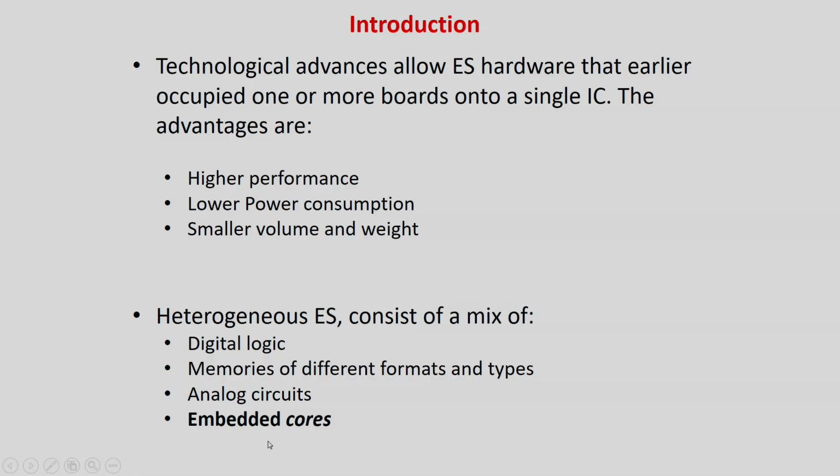Now if you have such a system, for some of the cores which I have designed, I have entire knowledge, I can put my DFT requirements, where to put scans etc., and I can make my life easy for testing. But think of the other cores which are purchased from other vendors. They are called IP cores, because nobody will tell you the internal details of their design. They will give me the processor and tell me what test vectors are required to test it, what the routines are, but they will not give me any more details. So I cannot change it in most cases, I cannot put additional DFT, but still with the existing test vectors given to me by that vendor, I have to test it in entirety.